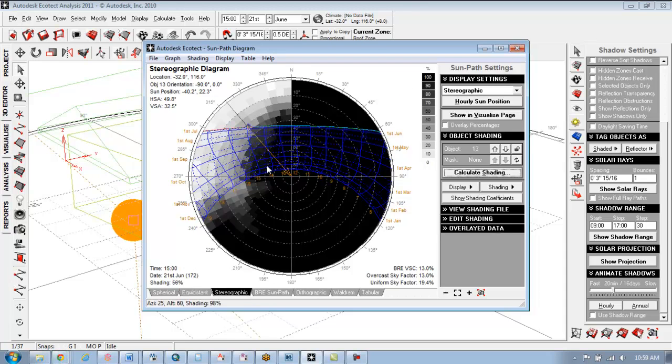Okay. But anyway, so you can see that because this window is on the east side, you don't need to worry about it. Well, again, we're in Australia, so everything's reversed right now. But obviously, there'd be no sun coming in as soon as it gets overhead and passes that window. But then you can calculate at certain times of year what the actual shading is going to be like, whether it's going to be shaded or whether sunlight's coming in. And then you can tweak it.